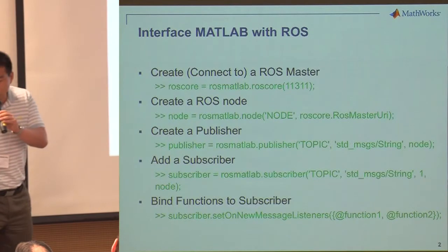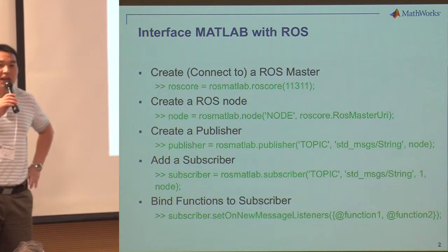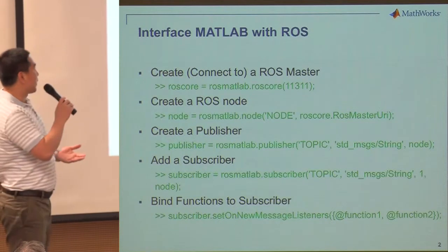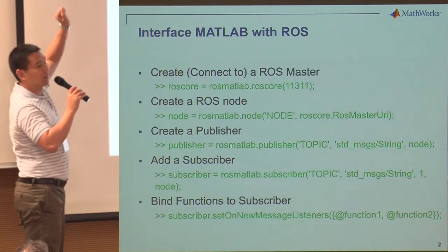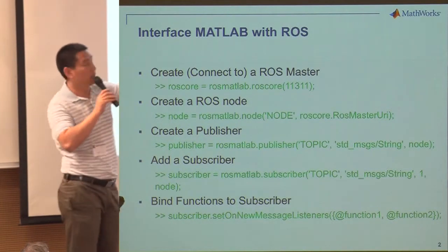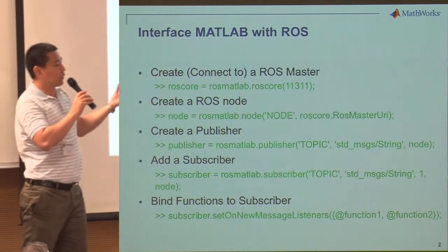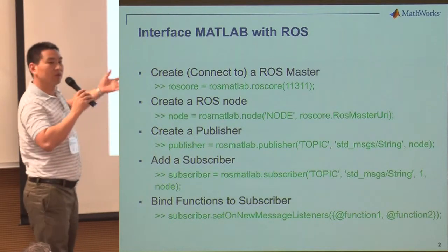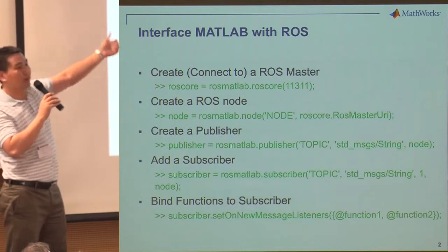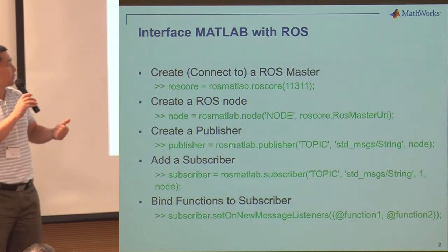So now, without talking too much, I'll show you how to quickly and easily interface MATLAB with ROS. First, I assume you already downloaded the MATLAB ROS integration package. Inside MATLAB, the first line creates an object called ROS MATLAB from the package you downloaded. You can create or connect to a ROS master. If you don't have a ROS machine, you can use your own MATLAB to create a ROS master to learn and experience how ROS works. Or you can connect to a Gazebo, a real TurtleBot, or any device running ROS.